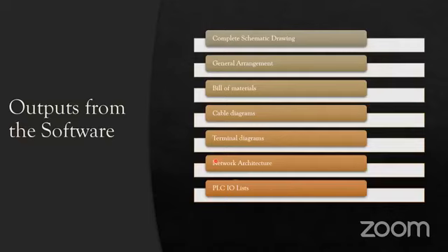So these are the automatically generated reports that you can get from the software. The schematic drawings you can design manually, or there is some software which supports automatic processing, where you can create one standard macro, and based on that macro you can generate your drawings automatically. You just have to fill in some data. Like if you have a motor feeder, you only have to fill in the motor size and cable size and everything, and then the software itself will generate the drawings automatically.